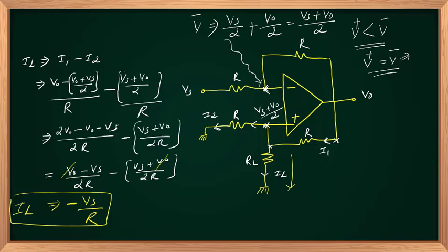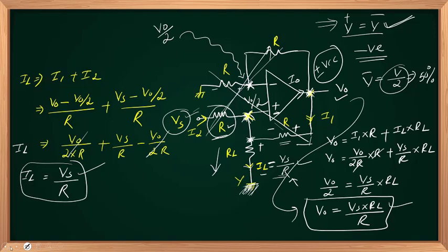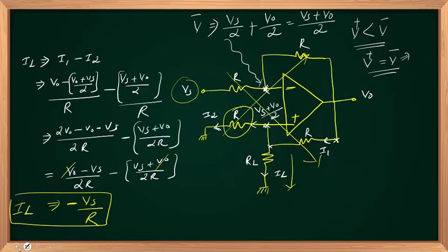So here also the cross product is matching each other. And for this kind of circuit with the Vs connected to the negative input side, you can directly write IL as this voltage Vs divided by R. That value of R is the same resistance as earlier, right? Not this resistance, right? The confusion regarding the resistance value will be clear after discussing the next problem.